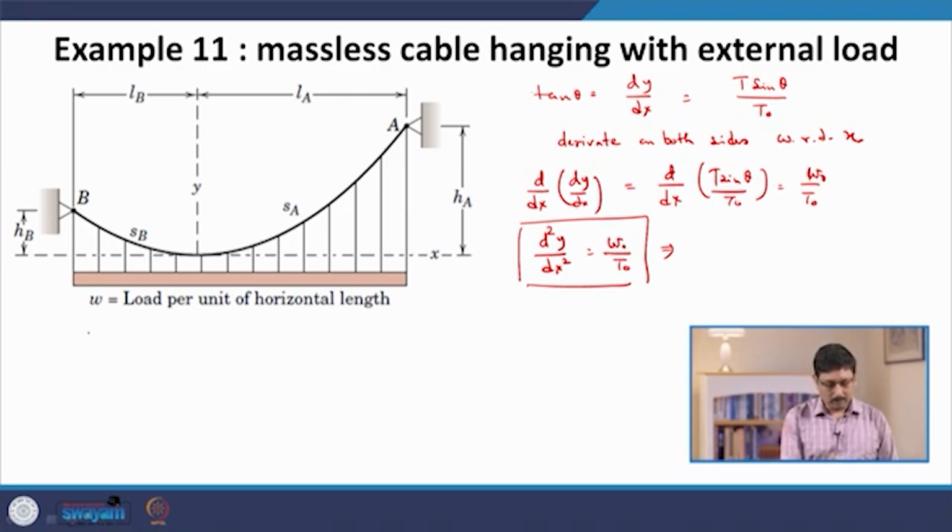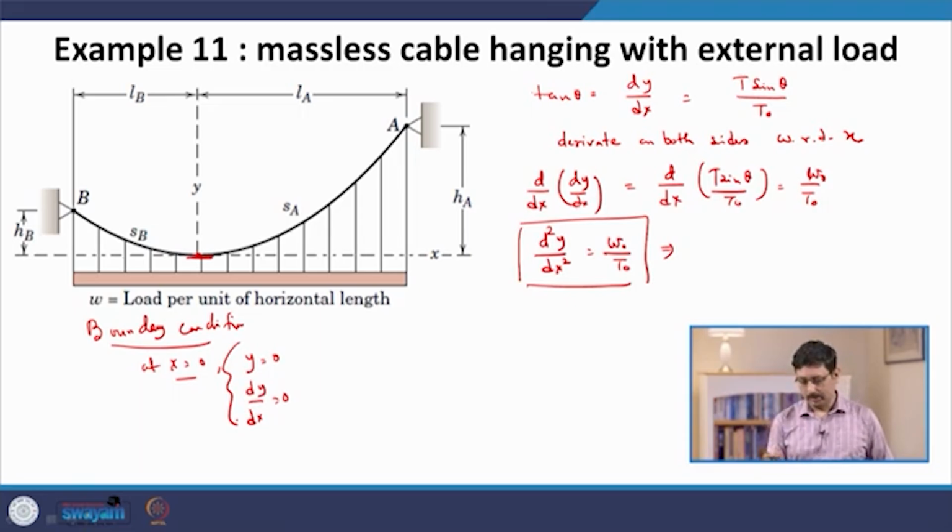So, here is where you need the boundary condition, because there will be constants of integration, and to determine those constants you need some conditions. This is where our choice of reference system comes in handy. So, at x equal to 0, y is equal to 0 and the slope dy/dx is equal to 0. This is our boundary condition.